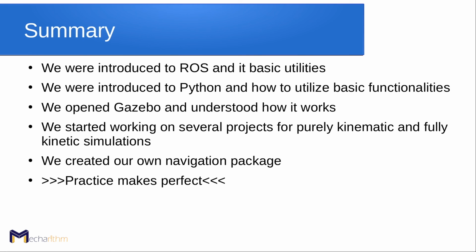We also started working on several projects for purely kinematic robots like the TurtleSim simulation, and fully dynamic simulations that include all the physics of a real environment like Gazebo simulations. We also created our own autonomous navigation package with aspects like SLAM, simultaneous localization and mapping. We created some maps and we used move_base, which is basically the control module, and we used some other path planning utilities, and we created a fully autonomous navigation package for a robot.